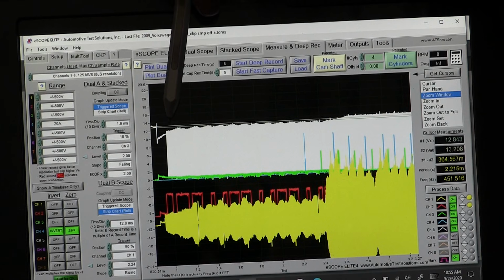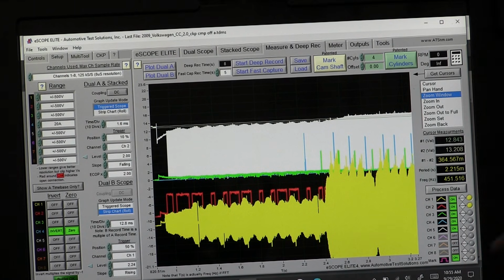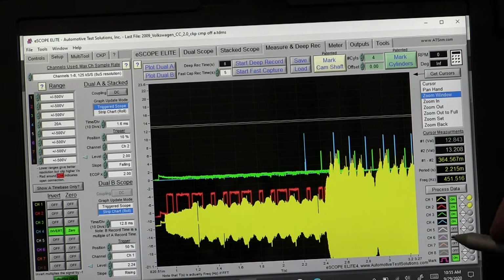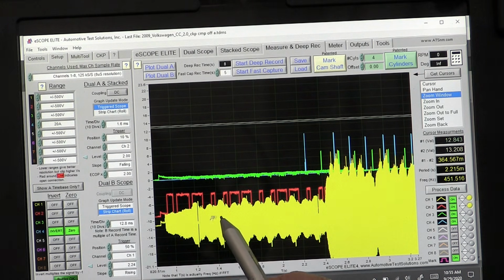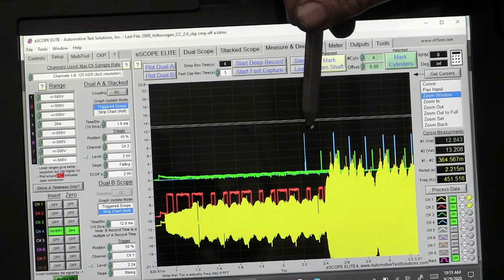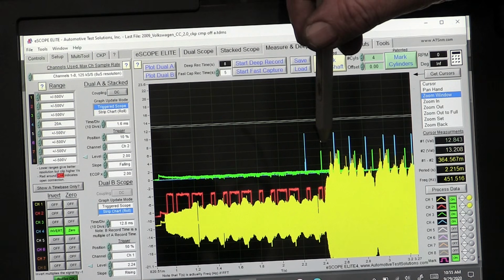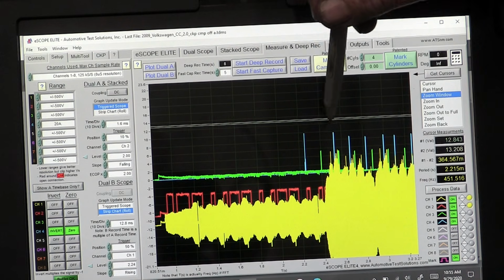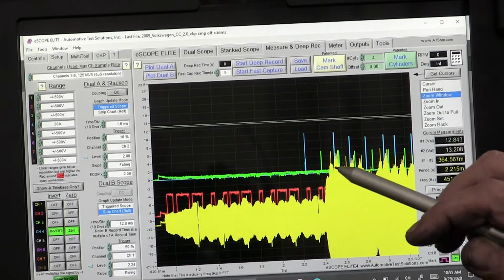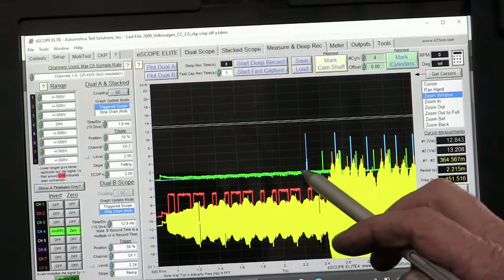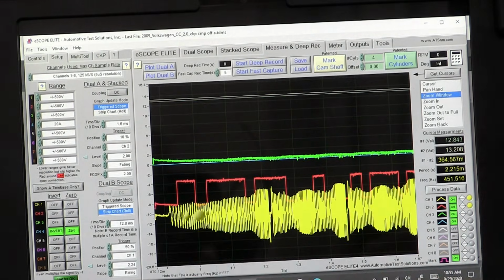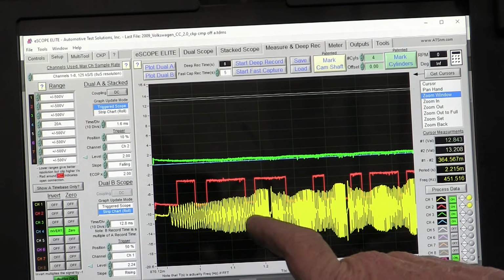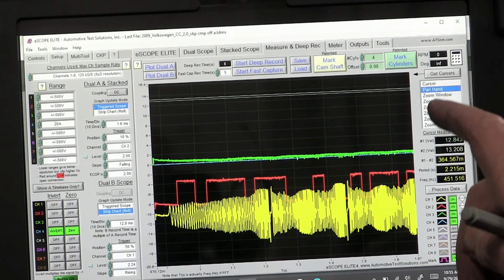Okay, so the white is from the VCT solenoid, so I'm going to turn that off for right now and come back to that. Now, look at how many revolutions I went. Multiple crank cycles before I got one event. This is the injector, and this is the coil. And once I got an injector and a coil, then we started. Now I already know that there's a problem because this should happen right away. So if we come over here and we blow this up, we can see where the crank started to go, and now I have one full revolution.